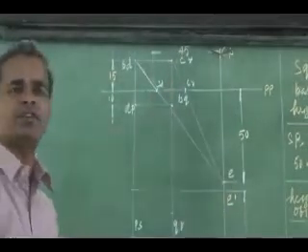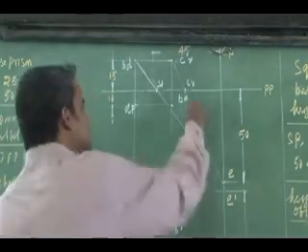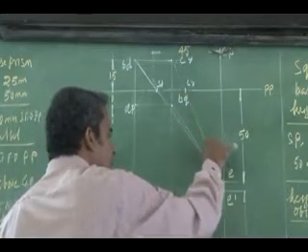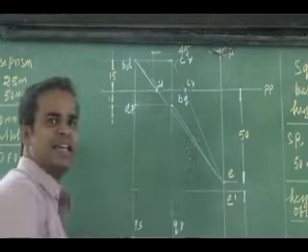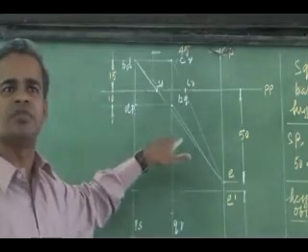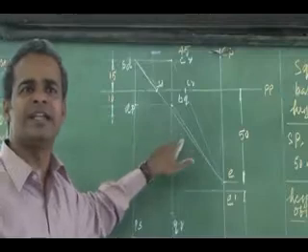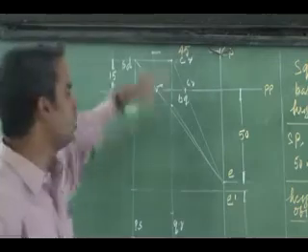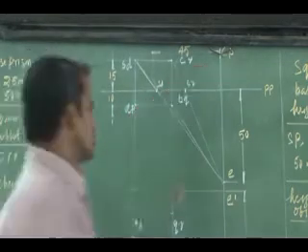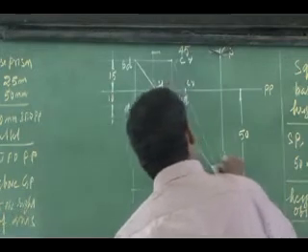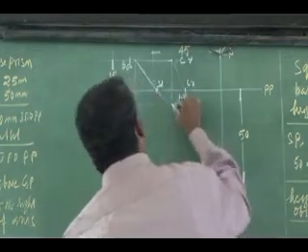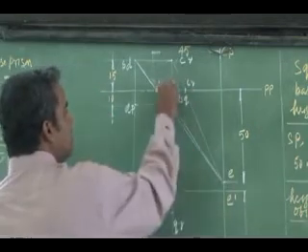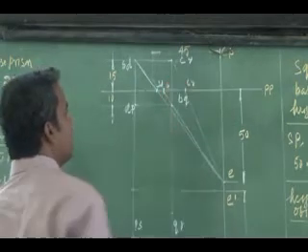BQ and AB. Suppose I join BQ. Listen all of you, this is important. Suppose I join this BQ with a visual ray line. Does the visual ray line intersect the picture plane? It is not intersecting. To get the intercept, I can extend it in the same manner, so the same visual ray line can be extended in the reverse direction. Where it intersects the picture plane in the reverse direction, that is going to be the intercept of BQ.